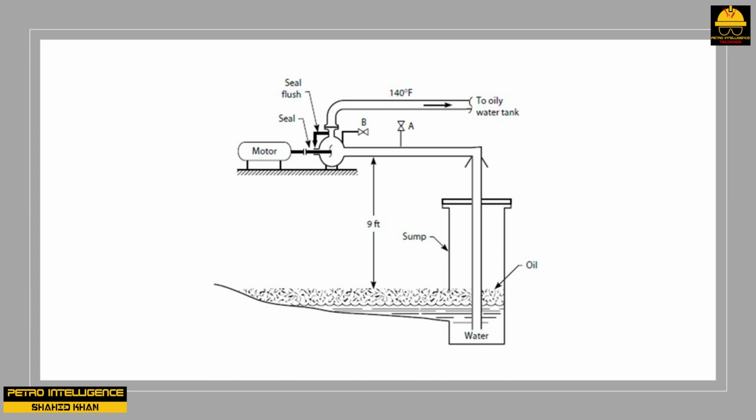Air may be drawn into the suction of the pump through leaks in the suction line. One especially vulnerable area is the packing gland around the valve stem of the pump suction valve. Another potential area of air in-leakage is around the pump's mechanical seal. Air drawn into either area will cause the pump to cavitate and lose its prime. The flow through the pump will then be lost. Playing a water hose over a leaking valve stem packing gland or over a bad seal can temporarily restore the pump to normal operation. Even better, spread grease on the leaking valve stem.